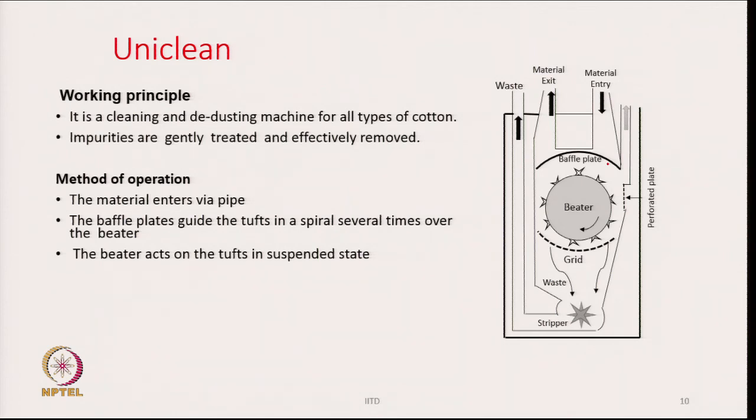Tufts are in free flight. So, they enter through this and they are acted upon by the beaters. In the same fashion, the trash particles will fall down and the cleaned-up material will move out as shown by the exit.